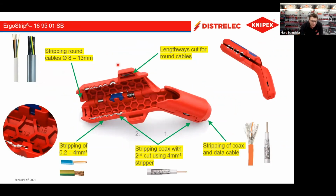We have here an additional blade for the length cut for round cables. So if you want to strip longer parts, you can use the length cut. The shorter side is for coaxial and data cable. For coaxial, you make the first cut in this part. And we have stripping holes from 0.2 to 4 square millimeter in these blades. And the second cut for coaxial cable you do in the hole of 4 square millimeter. I will show this later on the camera. So this is the Ergo Strip.